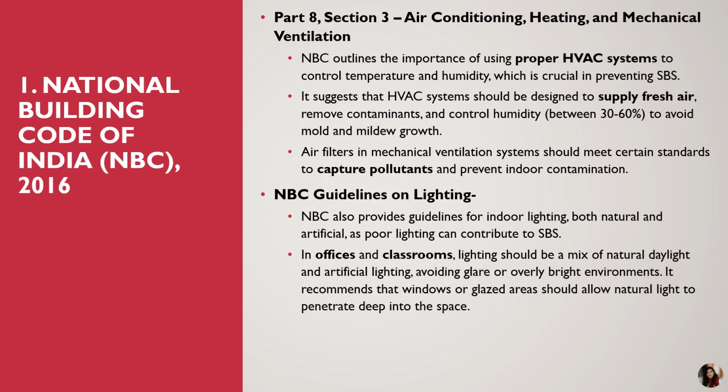Now, based on this part, Part 8, Section 3 says that there should be a proper HVAC system to control temperature and humidity, which is very crucial to prevent SBS. They suggest a design with equal exposure to a supply of fresh air, which will help remove contaminants and control humidity at around 30 to 60%, to avoid mold or mildew growth. Air filters in mechanical ventilation systems should also meet certain standards to capture these pollutants.